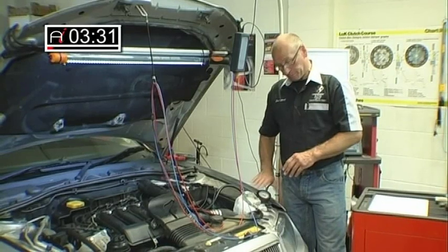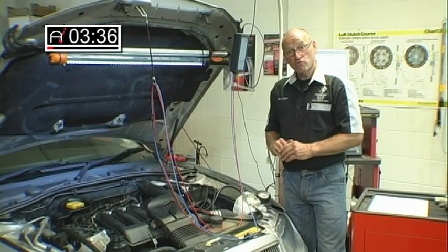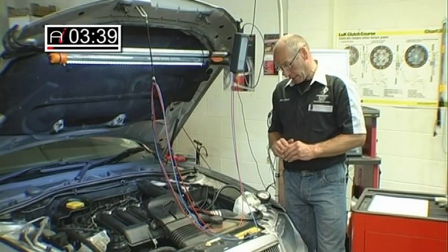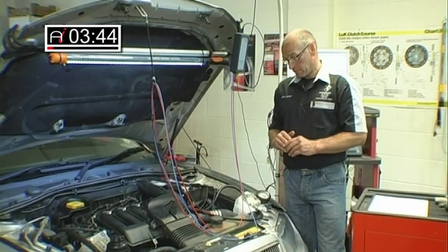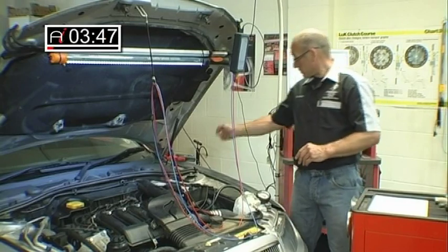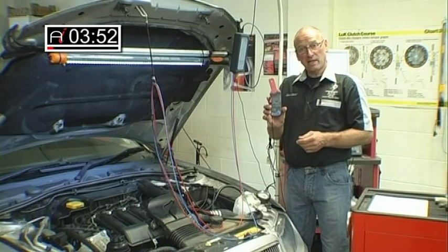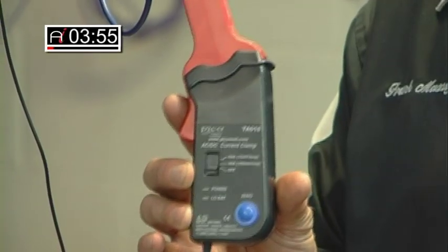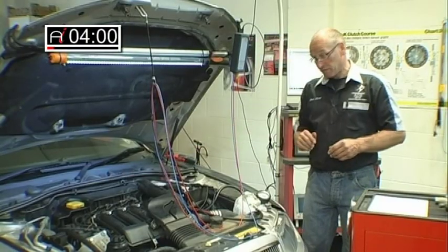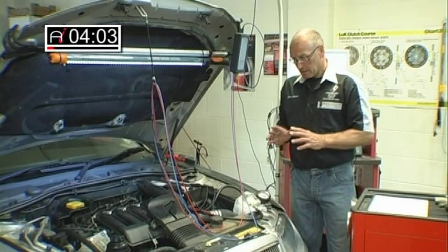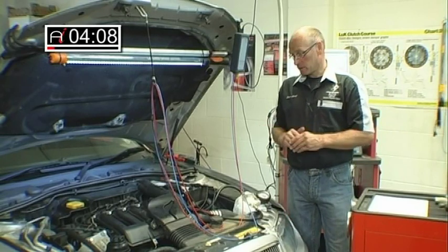So priming pressure is one of the things that we're examining. We're then going to take a look at rail pressure interpreted electronically by interpreting the voltage path from the rail pressure sensor. We're also going to be measuring current through the injectors using a Hall effect inductive clamp to evaluate how the injectors are being driven electronically, and as a result of that we should then quite easily be able to determine what the cause of this problem is with a no start condition.